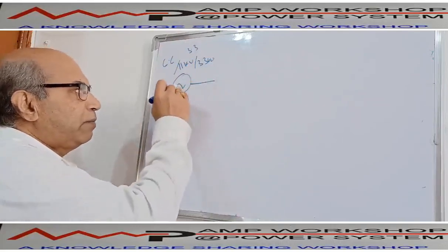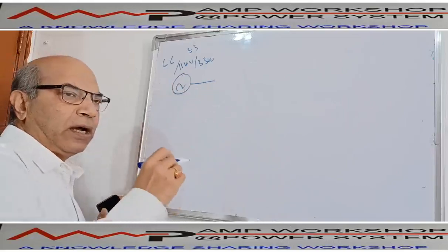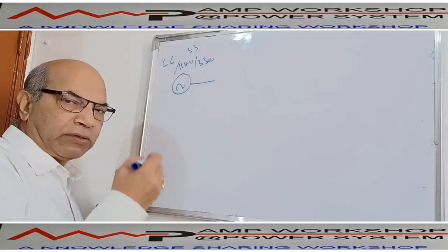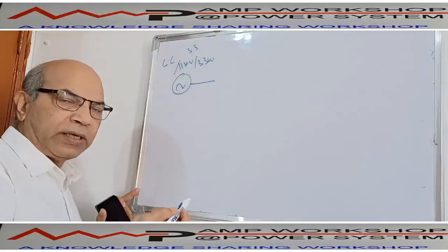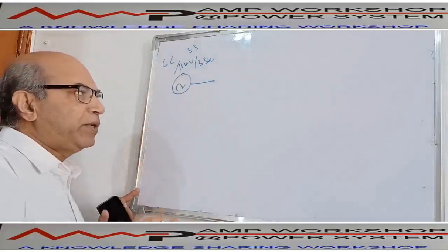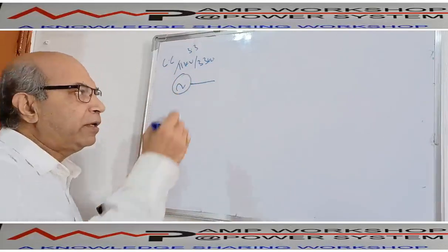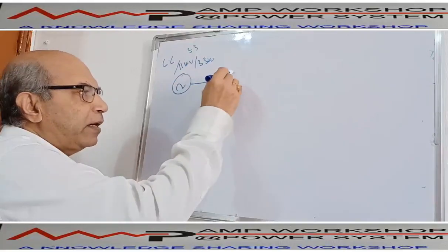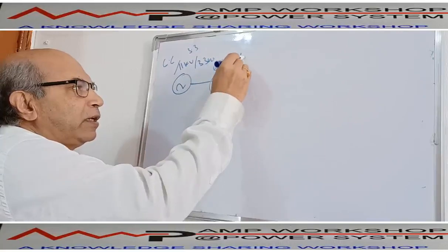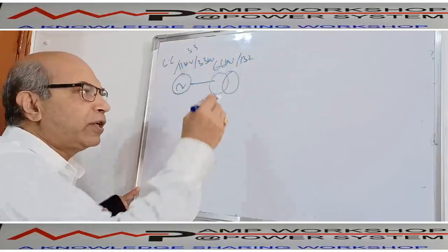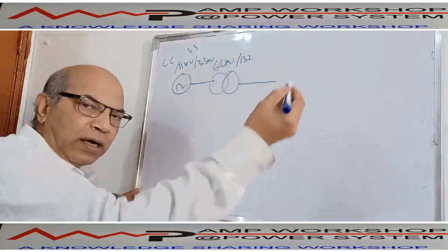Sometimes this generation is directly used, but in most cases, when a distribution network operator (DNO) is present, as well as power generation companies, the power generation company generates the power and then steps up the power to a high voltage, which could be 66 kV, or 132 kV, or 220 kV, or 400 kV. This stepped-up power goes to the remote end.